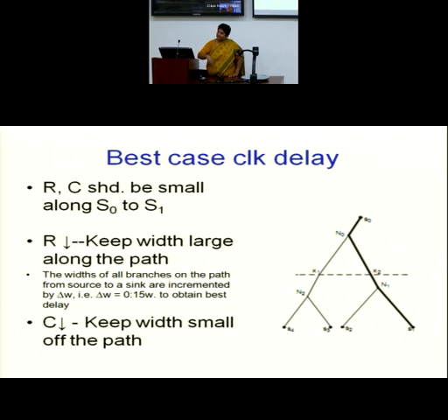And then again repeat the same process. So this is where I am designing my wire segments. What I have done is that I am determining the length of the segment by determining the number of isoradius levels, and also by looking at the process variation sensitivity to my skew, I am deciding for my wire width. So I have decided for every segment the length and width. T we do not change.